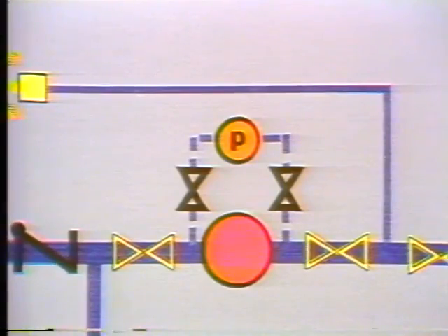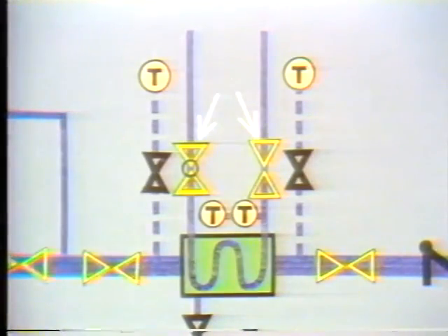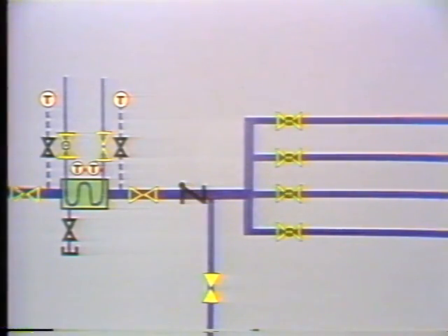Are any isolation valves shut in the main line? Or are any of the check valves in the main line stuck? Is the differential pressure reading across the strainer too high, indicating a blocked strainer? Are the cold water valves open to the proper position to cool the cooling water? But all of these possibilities can be checked in one step by checking for proper cooling flow at the other branch connections. If the components off these three branches are getting proper cooling, then it is not likely that the problem is anywhere in this part of the system. That leaves this portion of the system.